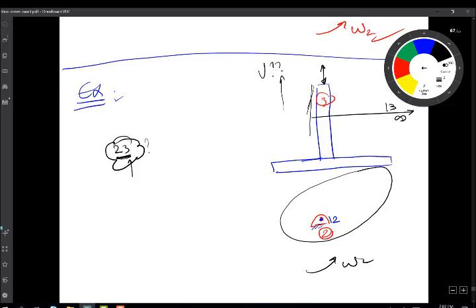So I'm after point 2, 3, or 3, 2 if you like. Now, if this is the pivot, point 1, 2, and at infinity I have point 1, 3, the common number is 1. So if I draw a line perpendicular to 1, 3 and to infinity, this will be the locus for 2, 3.